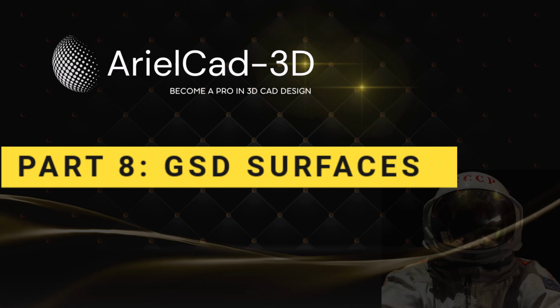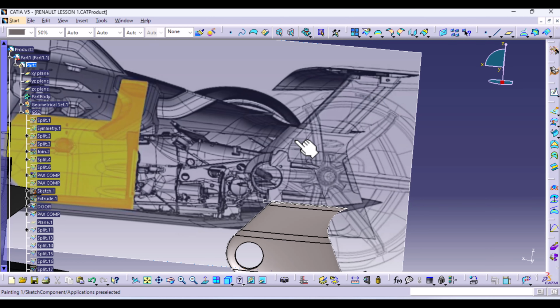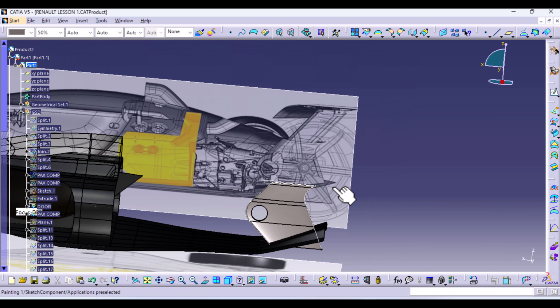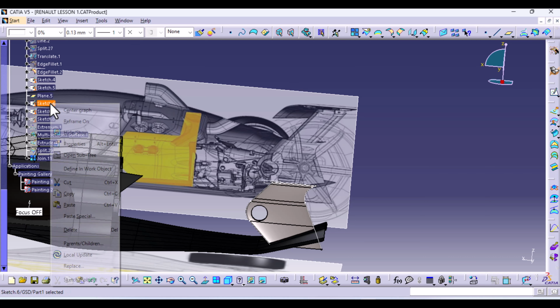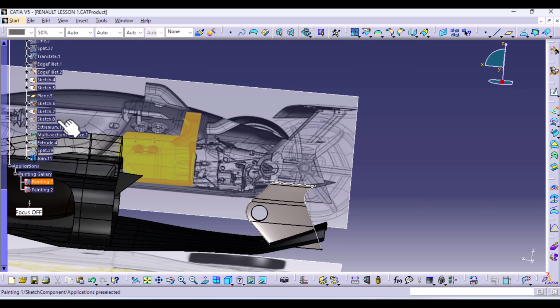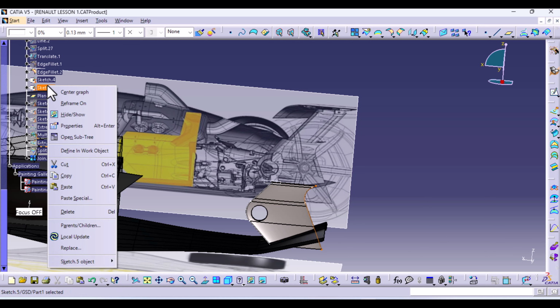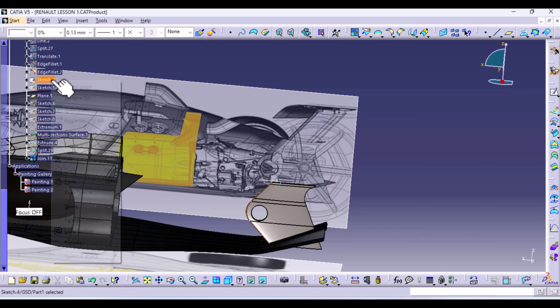The next part will be the retractable part, but we're not going to bother ourselves with the mechanics. We just create the feature and leave it hanging here. And we'll start by creating sketches such as what we did here. So we can hide these two sketches. It's sketch 6, sketch 7, we have 5, and sketch 4. All right, so once again, we are going to sketch on the ZX plane.